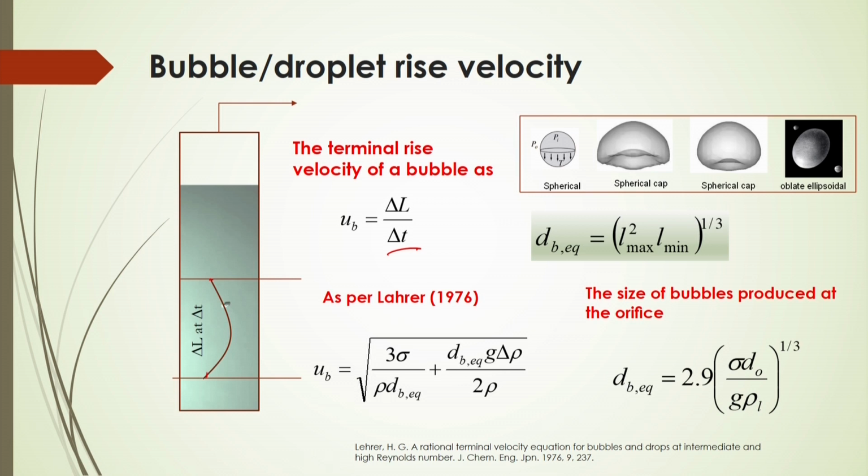So here, retention time, or you can say residence time of the bubbles, depends on the size of the bubbles. That is why in some processes it is one of the important factors you have to consider. Suppose in the same example, carbon dioxide gas absorption in the liquid.